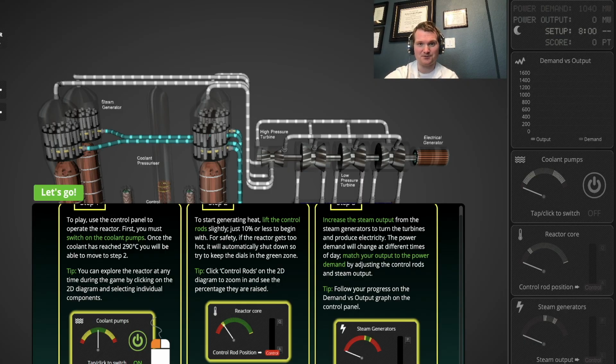So you're gonna need to either dilute the reactor coolant system, remove boron to essentially raise power, or withdraw control rods. And this is gonna raise temperature, to maintain power at that 50%, so xenon doesn't shut you down. And that's just a pain to work with. It's expensive because it involves using a lot of ultra-purified water to change reactor coolant concentration, and it just gets into a big mess. So nuclear power plants are not designed to be load-following plants. They're designed to be base load, where they get up to 100% power, and they stay there for 18 to 24 months at a time.